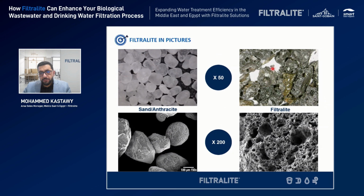While you can see in the right picture that we are also using the space between particles, but in addition to that, there is high porosity, or voids, as we call them, in the particle itself. It's totally different from sand and anthracite. With these particles, you can hold more suspended solids. You can give your filter a longer lifetime until you stop and do the backwash. So you are utilizing the full depth of your media.